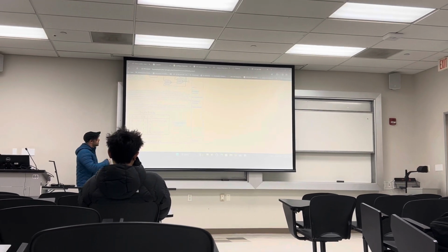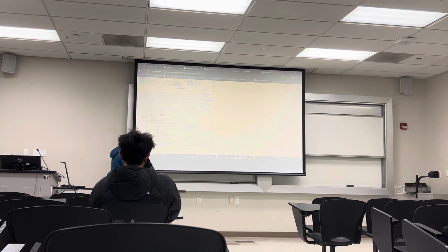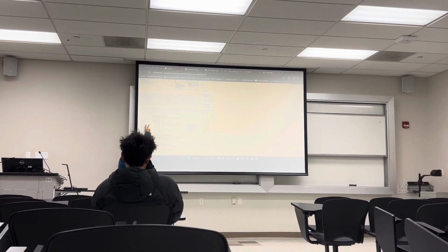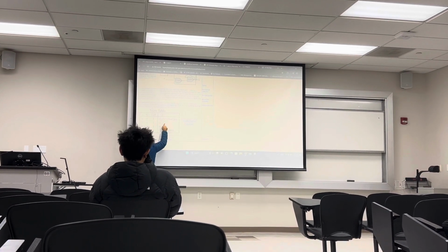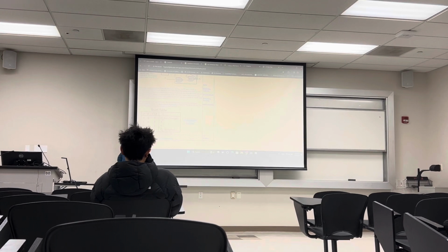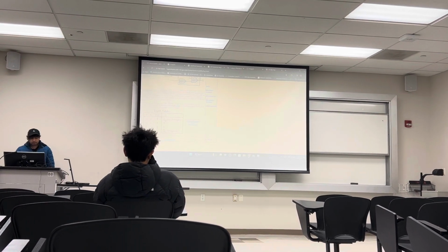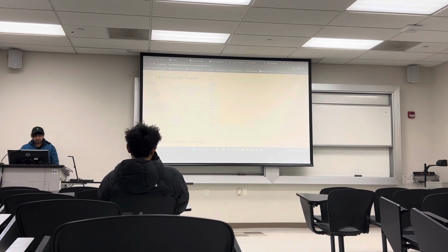So we want to use this feature for counting up and down. We connect both inputs of the JK flip-flop together, so the output will sometimes change or not change. We use this structure for our counter, for the 4-bit counter. Using this feature, we can design a JK flip-flop.